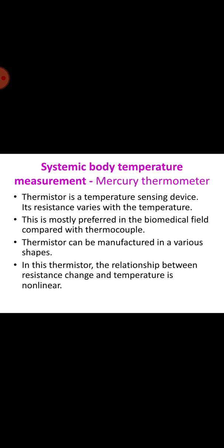The other measurement can be made by using a thermistor. Thermistor is a word derived from thermal resistor. These are a type of semiconductor, meaning that they have greater resistance than conducting material but lower resistance than insulating material. The relation between the thermistor temperature and its resistance is highly dependent upon the material from which it is composed. The manufacturer typically determines this property with a high degree of accuracy.